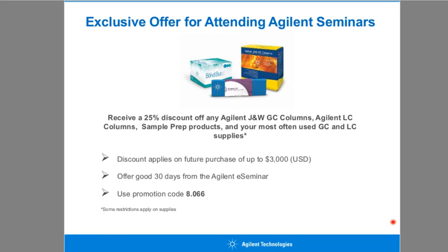So something like that you would want to use more of a 2 millimeter or a 1 millimeter ID liner just to get it, again, moved from the sampling valve of the sample loop at that point onto the head of the column. So if you're using a split inlet, I would go typically a smaller ID liner just so you don't go from a narrow tube basically feeding into your inlet all of a sudden to a really broad tube, your liner at that point if you're using a 4 millimeter ID, where things can kind of disperse and then focus back onto the head of the column. You want to kind of keep things nice and tight, so a smaller ID liner is what you'd want to use in a situation or a sample like that.